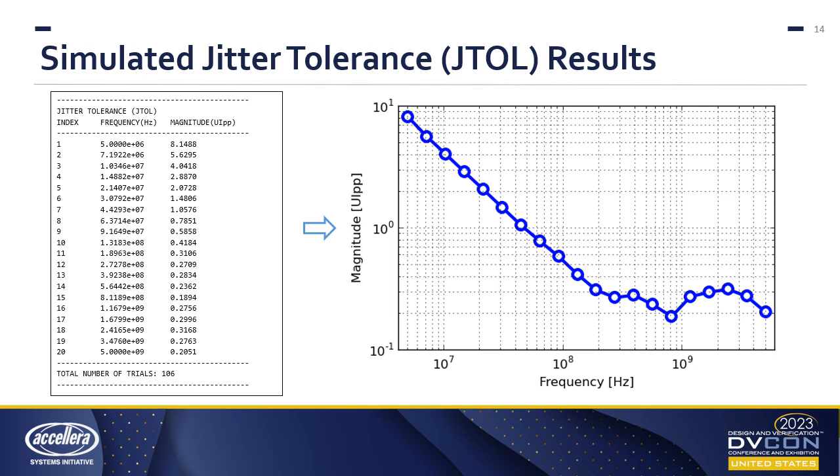When the simulation is over, the scoreboard reports the collected jitter tolerance characteristics in a table format. You can also plot the SJ magnitude versus SJ frequency graph, which visualizes the timing margin and tracking bandwidth of the high-speed wireline receiver.